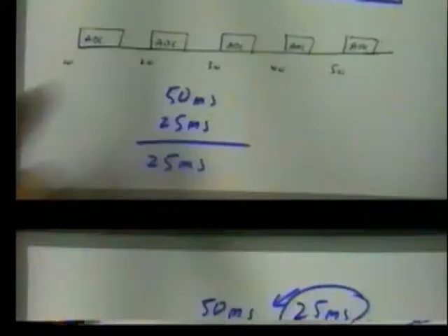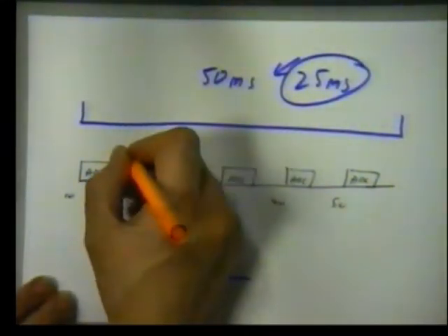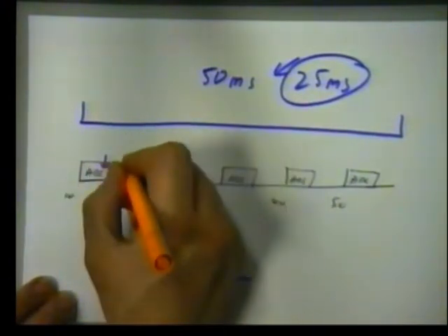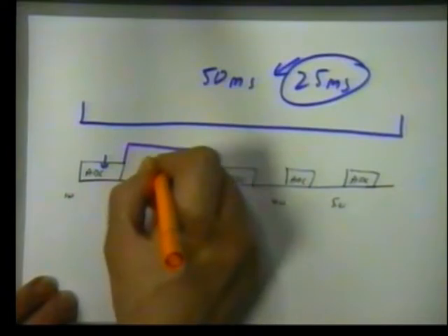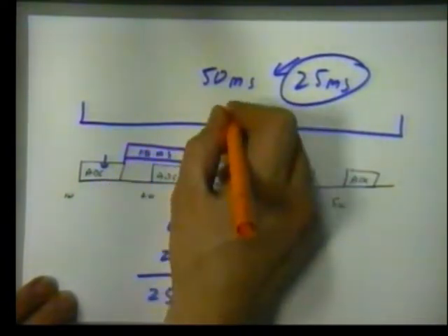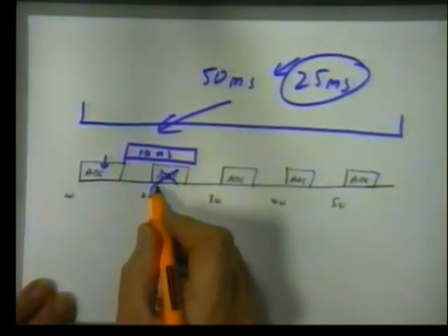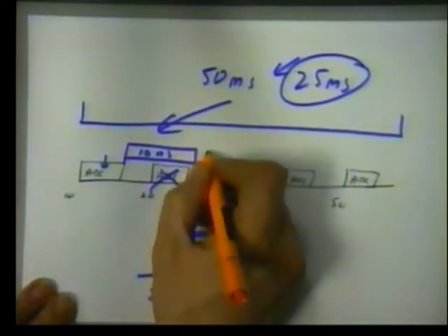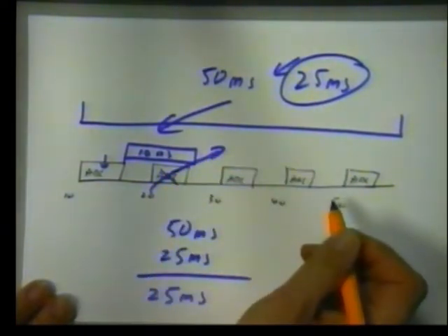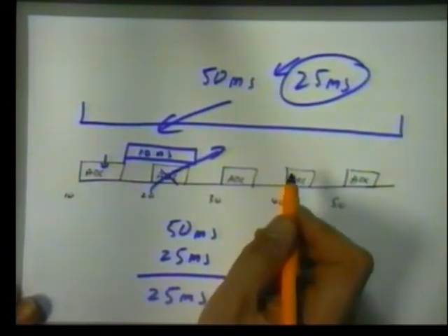Well, let's assume we've said, all right, every 50 milliseconds, there's 25 milliseconds spare. That's how long our other interrupt routine could be. Let's assume our other interrupt routine then took 10 milliseconds. Well within the time we've calculated. Now go back to the timing diagram. What happens here if we do our ADC routine and now we tack on a 10 millisecond external interrupt? What's happened to that ADC routine? It had to happen there. It was a sampling system. It's now going to be displaced in time to some time later. It's pushed forward. It's pushed out of the way.